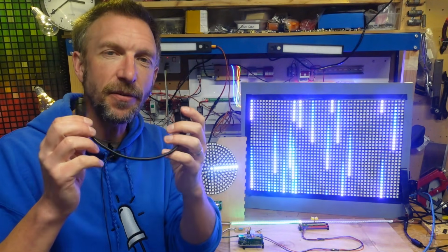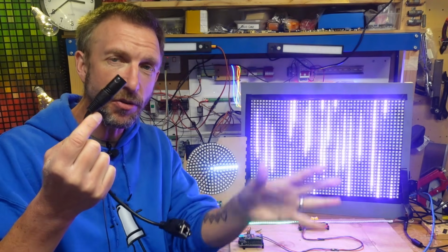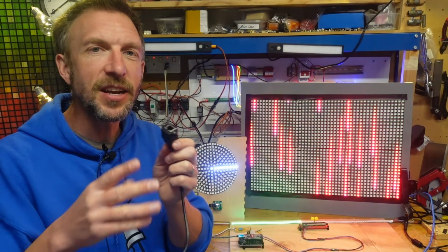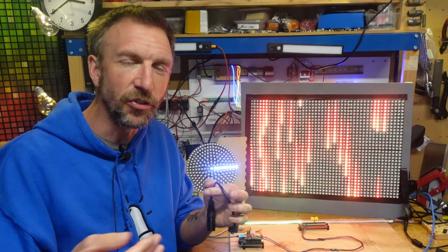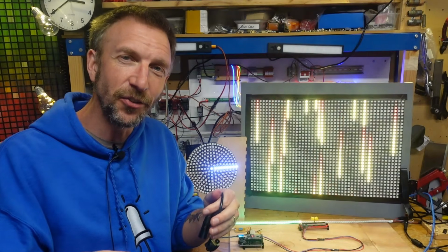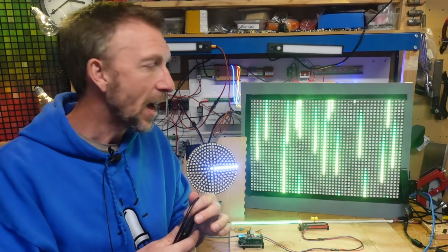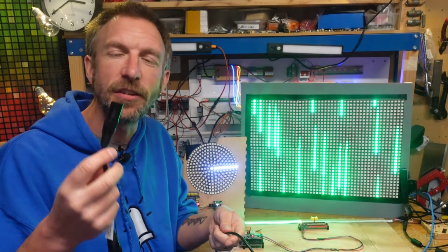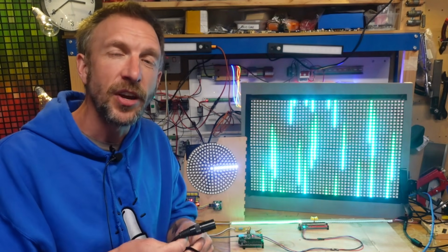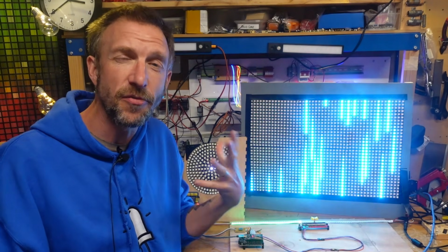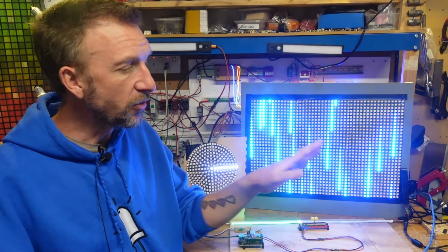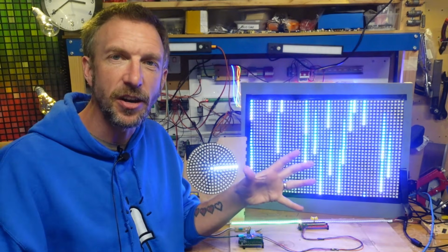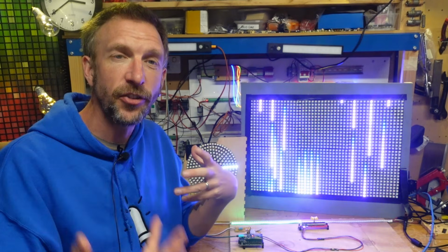sACN is slightly different. It delivers packets of data which still consist of universes, and each universe still has 512 channels, but in a single Ethernet cable you can send hundreds or even thousands of those universes, and the devices that receive them don't have to be daisy-chained together in series as they are with DMX. They can use a wired or a wireless connection to a regular Ethernet network. So just using a PC and a network router, you can have as many lighting nodes as you want, all controlled centrally.